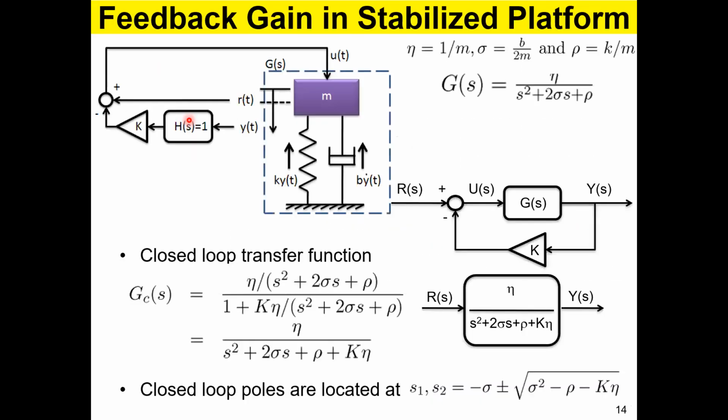If I pedal back, it's over here now, UT. We are issuing commands. It's somewhat easy to issue the commands, but it's difficult to implement them. Therefore, we need to keep an eye on the actuator. Every plant has an actuator. So the actuator gets varying commands in a dynamic situation, when the signals loop around it, and every loop there is a command coming to the UT. So it's important to know what these commands are. Then we can judge whether the controller can handle that. If not, you have to replace the controller with one capable of delivering that. Maybe speed, maybe the dynamic range, maybe the resolution. You have to pick the proper actuator to get the response that you need.